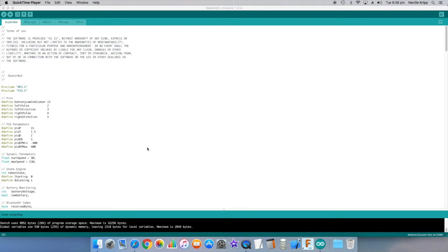In Dupe's project, he basically just provided all the code in line. I've taken a slightly different approach. I've broken out some of the major pieces to a couple of different classes, because I want to reuse this code in the self-balancing skateboard. So I thought it best to just break that code out now. So I've encapsulated the MPU code in a class of its own and also the PID code in a class of its own. So I might just start with that.